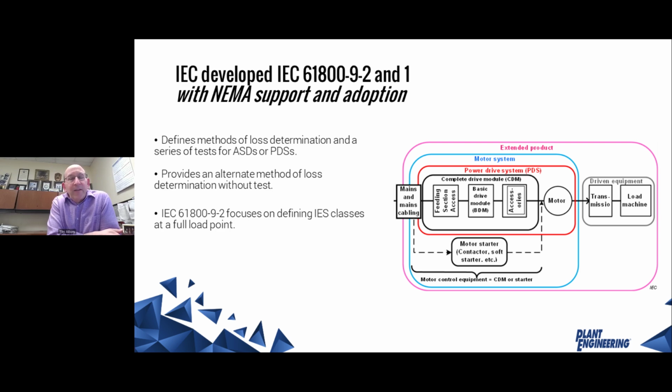But I would tell you that you don't necessarily have to get into that level of detail to understand the energy savings that you got. And I'm going to talk a little bit about that in the future. But NEMA has a power drive system standard, which helps calculate savings, which is actually simpler than the 61800-9-2, but it also doesn't account for anything except variable torque. So the NEMA standard is just variable torque. This standard from IEC can do pretty much all different types of applications.